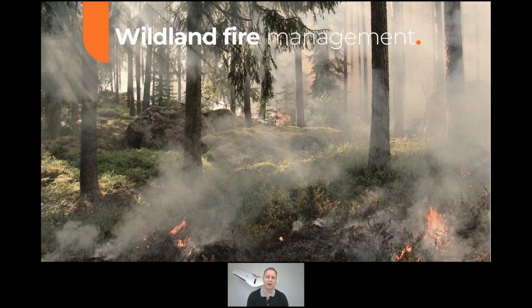If you're talking about live wildfire operations, and I come from the Western U.S. where this is a big topic, you're almost always going to have a lot of air traffic. You're going to have other tankers, and you're going to have helicopters in the airspace. If you even want a chance of being authorized to fly a drone in that airspace, you're probably going to need at minimum ADS-B in and out, so you can tell other traffic where you are, and so you can see where they're at.